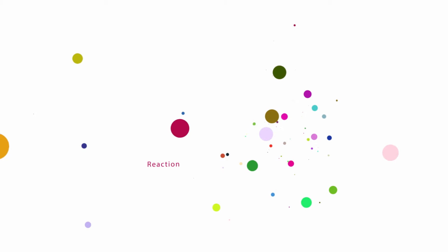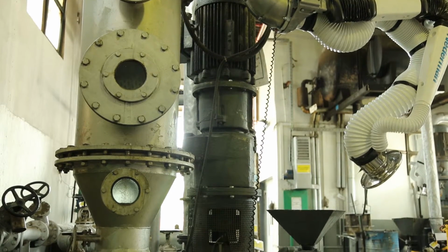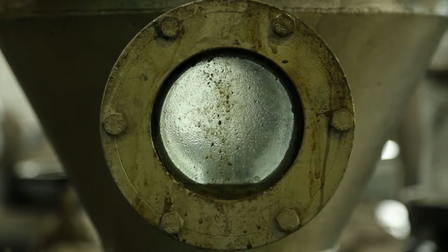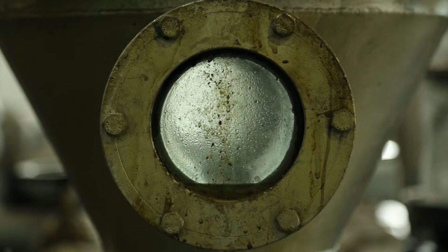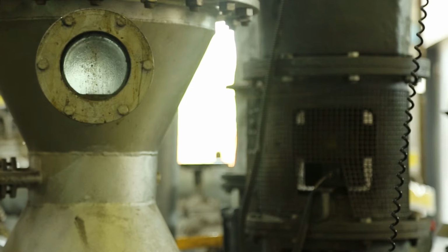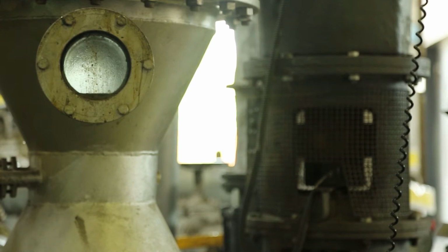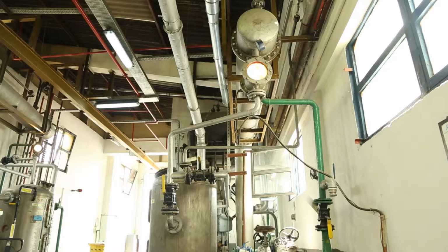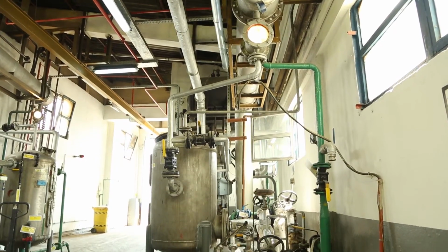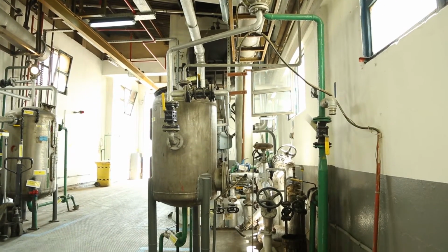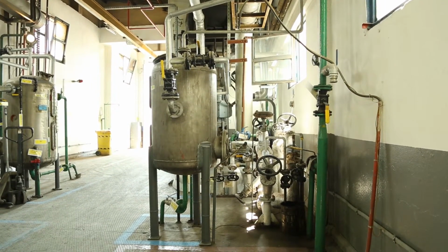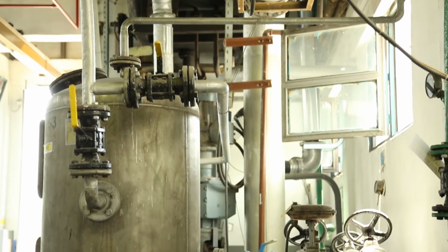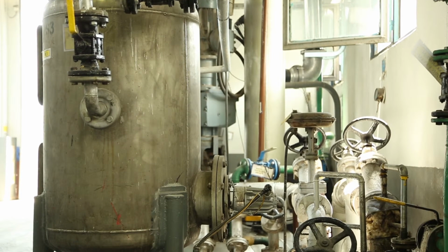Reaction. After feeding catalyst, the reactor is heated slowly to initiate the reaction. During the reaction, the reactor is continuously heated. In order to maintain the desired reaction temperature range, the reaction is continued by heating and cooling at necessary levels. Average reaction time is 16 to 20 hours. As a result of interim controls, if desired product specifications are reached, then the reactor is cooled down to complete the process.